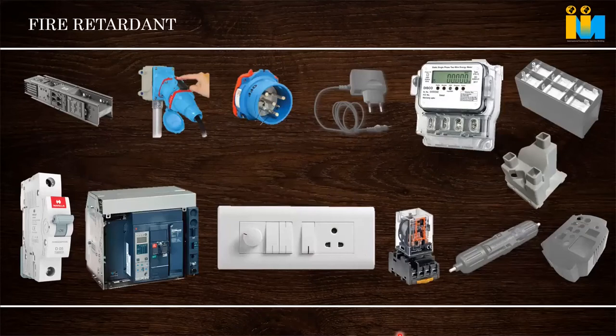We have discussed flame retardant means if the part catches fire, how quickly it should extinguish. This is the flammability property. Basically, this comes inside the raw material itself. Suppose polycarbonate SABIC grades, we say 123R is non-flame retardant, but 945, 943 is a flame retardant V0 grade. It means it quickly extinguishes the fire.